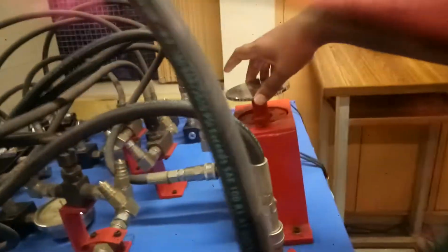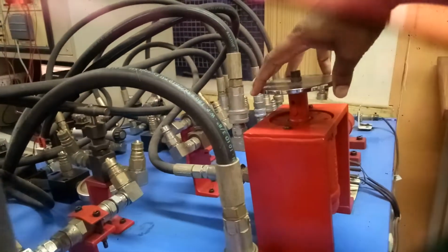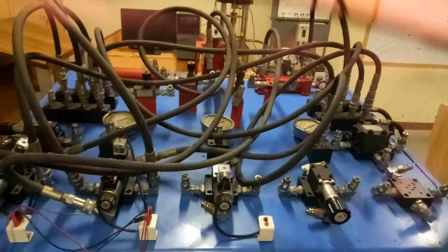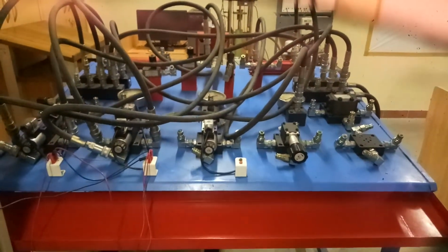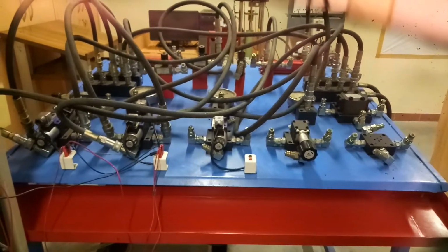For the other one we go for the rotary type instead of the linear one, that means clockwise and anti-clockwise rotation. That can be considered a rotary actuator, and this will be the linear actuator. We can take it as one of the double acting cylinders. In the clockwise direction, that will be the extension, and in the anti-clockwise direction, that will be the retraction. That way you can give the connection to the two double acting cylinders.